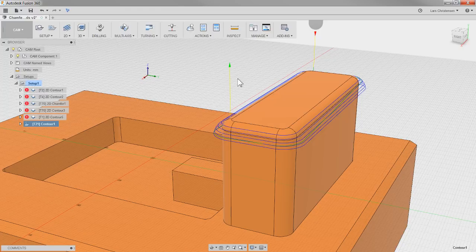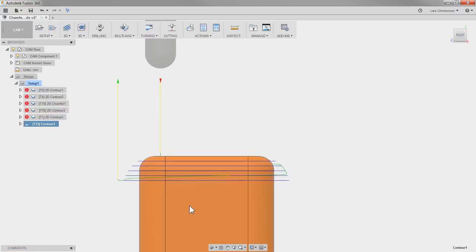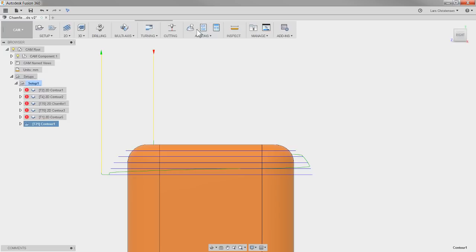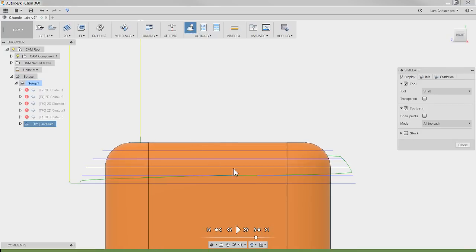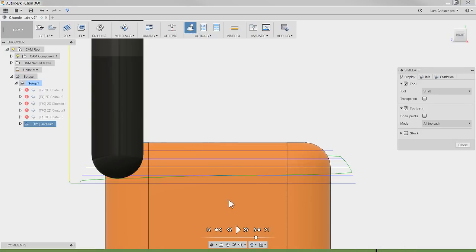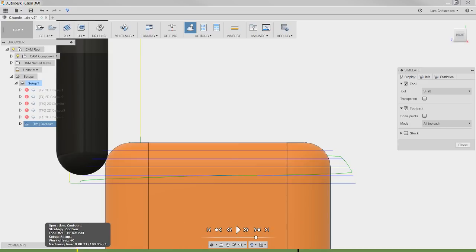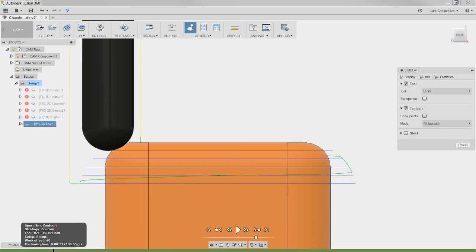Now, by checking that checkbox, we're actually getting something. What are we getting? If I go in here and go normal 2, and let me simulate it, you will see that, let's go to about, so this is about where we selected that chain. Right now, the cutter sees that that's the center, and it says, I can't come past that.